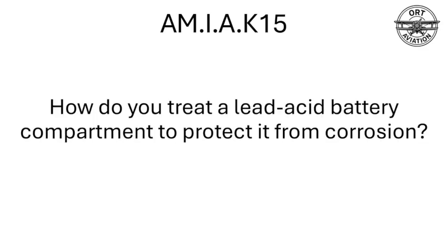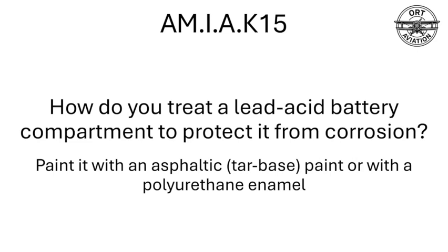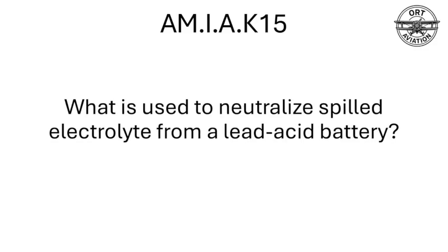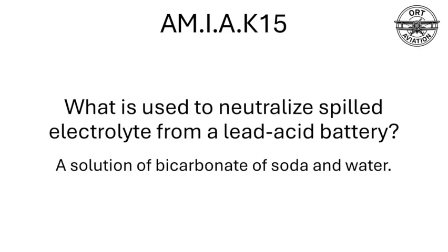How do you treat a lead-acid battery compartment to protect it from corrosion? Paint it with an acrylic tar-based paint or with polyurethane enamel. What is used to neutralize spilled electrolyte from a lead-acid battery? A solution of bicarbonate of soda and water.